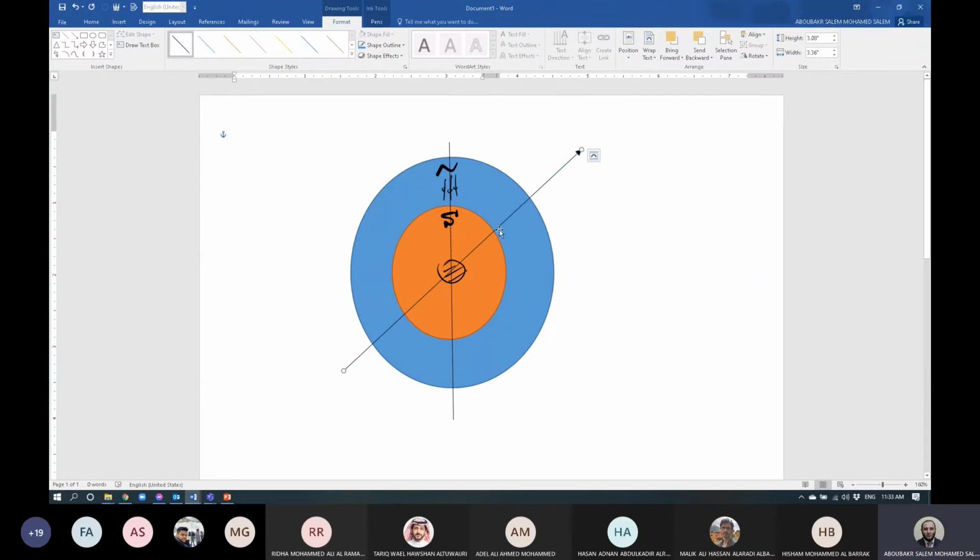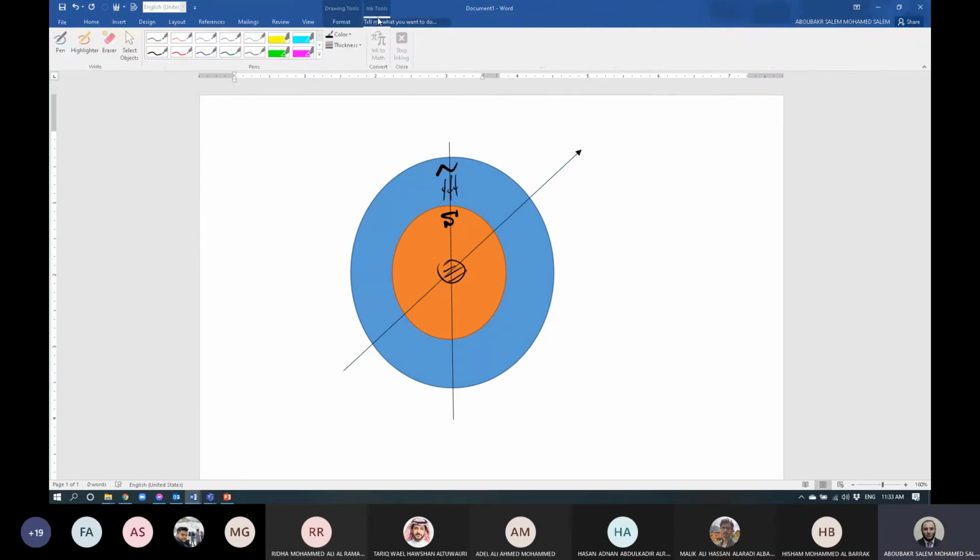So this means that the pole S here will be shifted to be in that point, and the flux lines will be stretched like that. تمام يا شباب? Do you got it? Yes. This is due to the load increase. Actually, this is the angle delta.